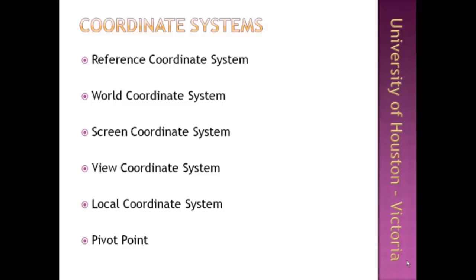The purpose of the screen coordinate system is to make it easy for you to move and rotate your objects primarily in orthographic viewports. However, you should note that working with a screen coordinate system in perspective view might mix up your intuitive sense about how you're viewing the scene, and it might be very difficult to get objects correlated and coordinated appropriately.